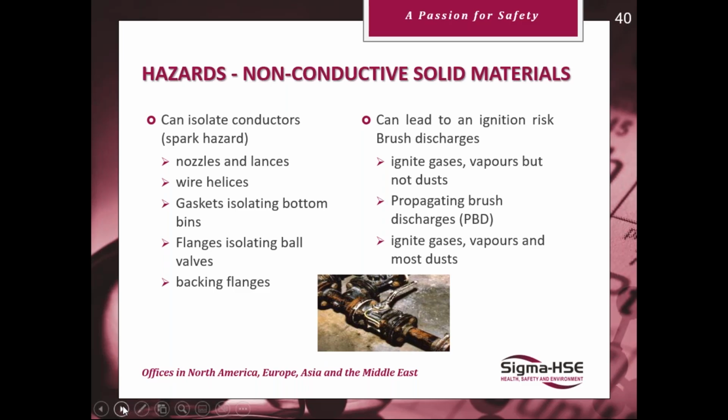Hazards: they can isolate conductors, and we get the spark. You can look at nozzles and lances, wire helices, gaskets, isolating bottom bins, for instance, and flanges which can isolate the ball valve, backing flanges, etc. This can lead to ignition from brush discharges from non-conducting materials, which can ignite gases and vapors.